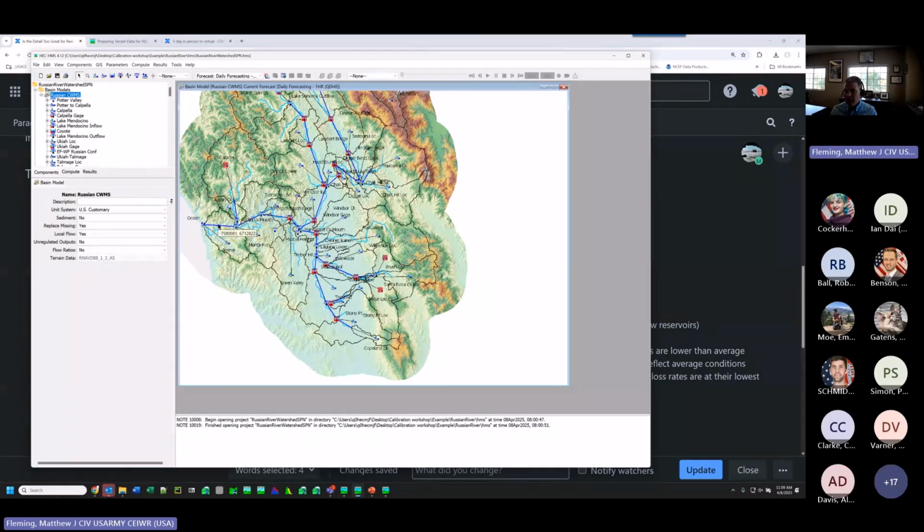And so to save time, I could have within this tributary just one zone, not a zone for each of these computation points or locations with observed flow. And then I would use the zonal adjustment to change all the parameters in this zone by one scale factor, right? So that would be a quick change. I can make that quick change and then really only focus on the results here at the outlet of this tributary. Okay, does that make sense?